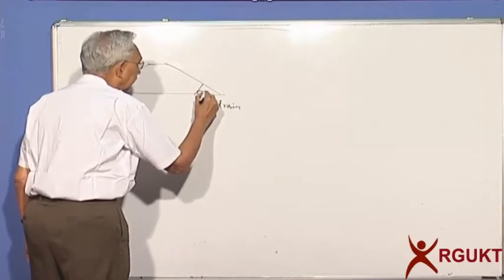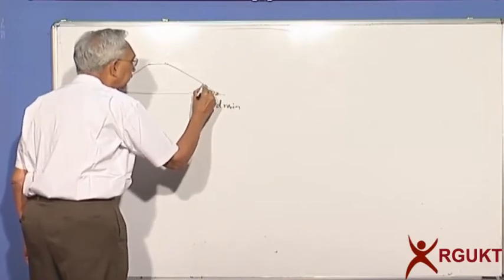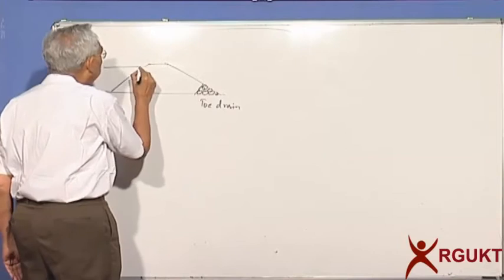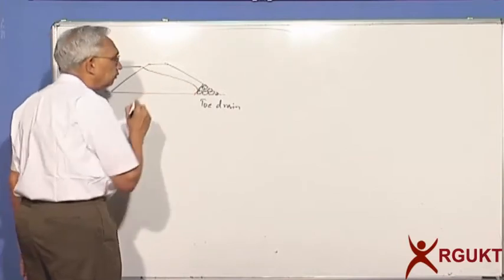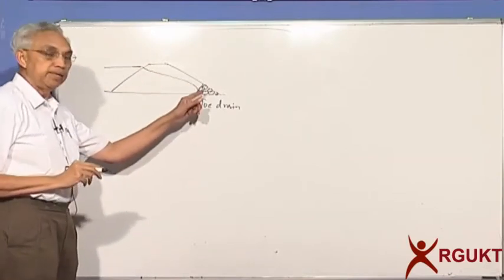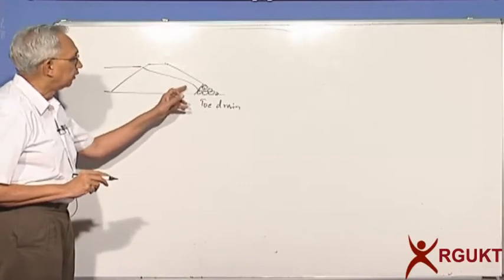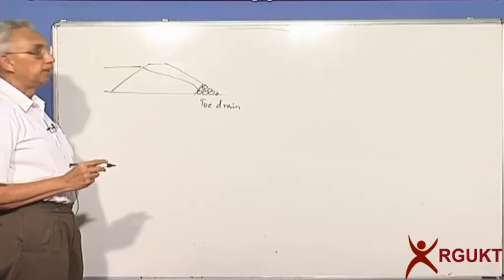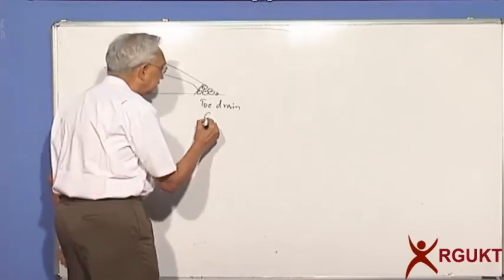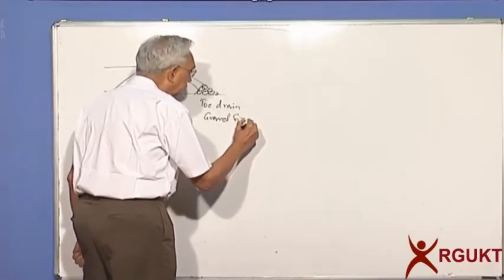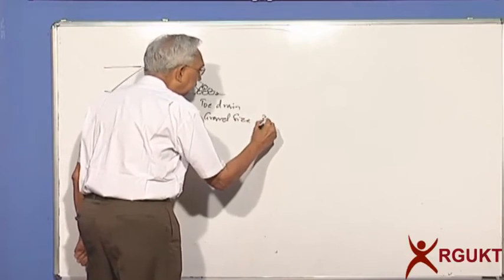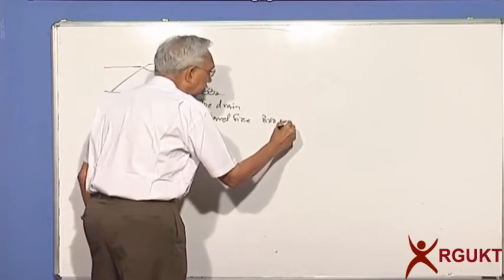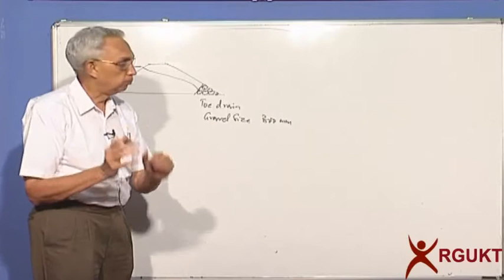So these are all gravel particles, so that when the top flow line comes, and this being a highly pervious material, water will have a tendency to get attracted, and so you provide, and the gravel size can be of the order of up to 300 mm. You can put large size gravel particles there.